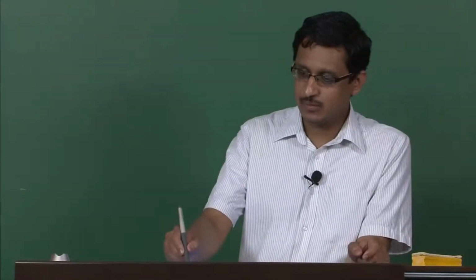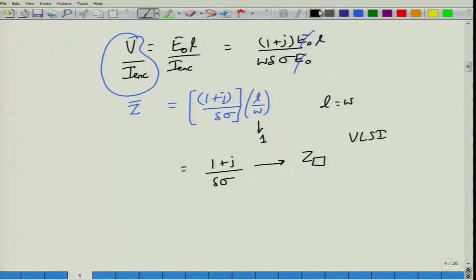This impedance that we have defined is defined by the potential difference to the current enclosed, right. There is another impedance which also turns out to be complex in this case. This is called the surface impedance. This surface impedance is defined as the field amplitude to the total current enclosed. So it is not the potential difference, but it is the field quantity.